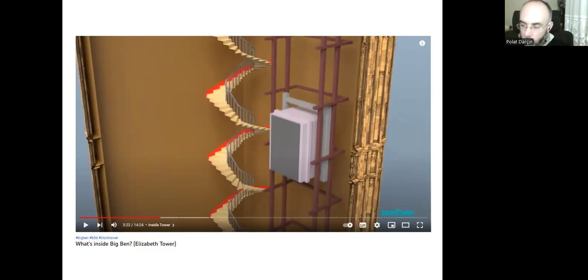We are going to place vertical columns or studs, and we need to connect them with horizontal beams so that the loads of the elevator will be transferred to that structural system. Then we need to connect these vertical and horizontal components of the elevator structure to the main structural system of the building.